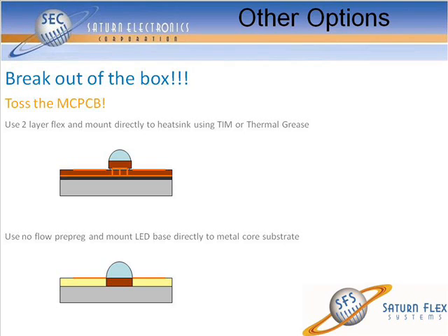A couple people will probably kidnap me at the end of the day in this audience, but it's an option. Like the presentation before us, we were talking about using expensive methods to plug vias and then plate over them. Add a little copper. It's so much more conductive than any dielectric out there. You could achieve the same thing. Just dissipate your heat directly with your vias.